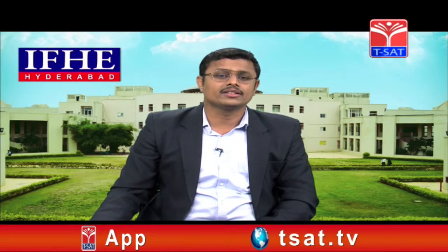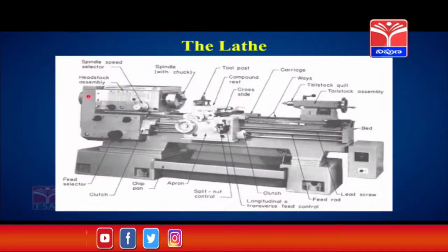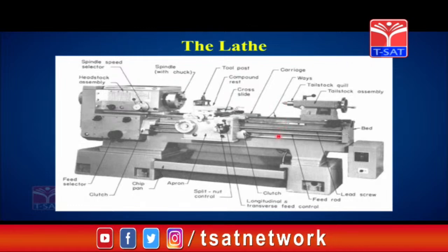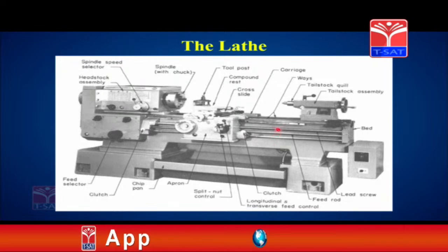The first one, you can see, is the headstock. All the cutting processes will be there, and this is called the bed. The lathe size depends upon the bed size and the chuck, how much diameter it can hold. This is the tailstock, where the dead center holds the workpiece, and this is the lead screw and feed screw. For threading, we use the lead screw, and we use the feed screw when continuous turning is there. So, this is called the lathe.